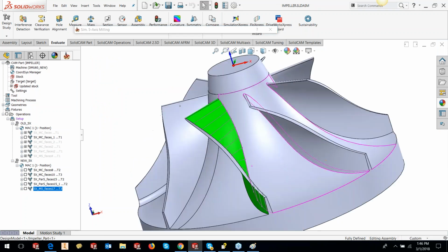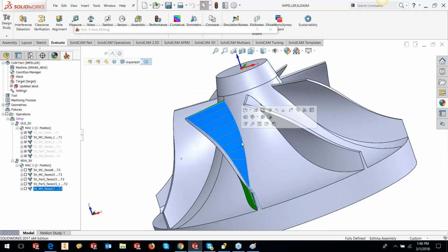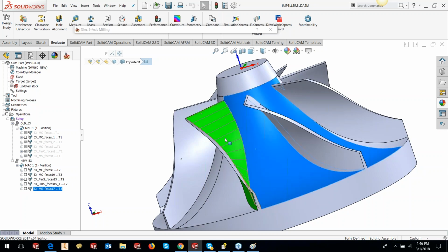The first gouge check in this case should always be the tilt, because if you say check the bottom first and then check the tilt, it will check the bottom first, ensure that there is no gouge, and then it will try to tilt the tool. The moment the tool is tilted, there is every possibility that the tool can again gouge at the bottom surface, and it's not going to check the surface again because it's already past that phase.